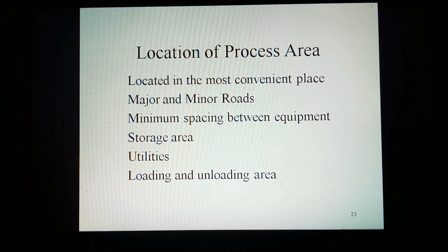The plant may contain one or several process units. Where any unit processes flammable fluids and may be operated independently, i.e. one unit may be shut down with others in operation, the minimum spacing between equipment on the two adjacent units shall be at least 20 meters. The storage area shall be located as far as possible from buildings occupied by personnel at the site, but should be located near the process area for ready operation of the feedstocks and product rundowns.